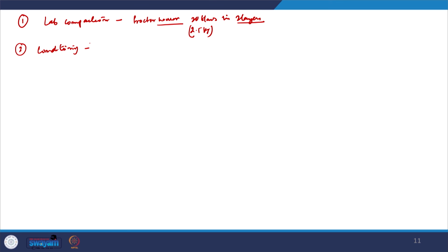So, one way is to keep it undisturbed for 24 hours, and then you can condition it under water for 27 days.